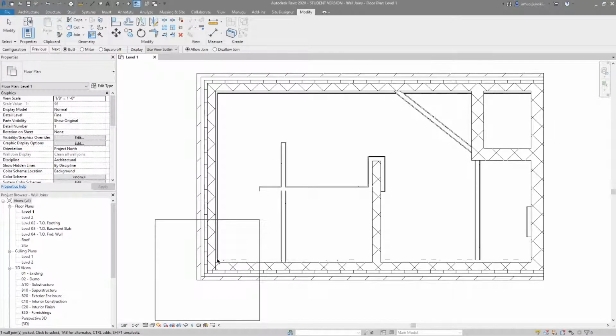So as far as the display, I have the option to do a clean join or to not do a clean join or just use the view setting. And again, this is another situation where oftentimes I find myself just simply using the view setting because that is the default option, and very rarely do I find myself having to actually go and say, oh, I need the clean join, or I specifically don't want a clean join in this situation.